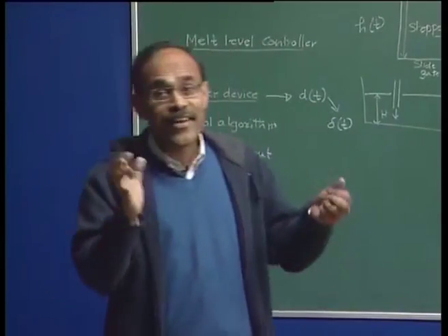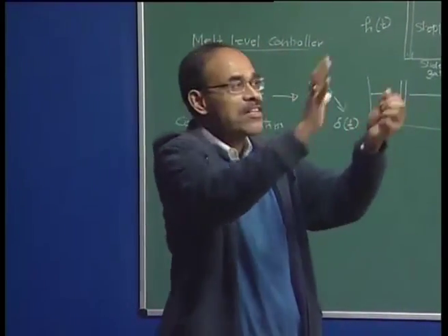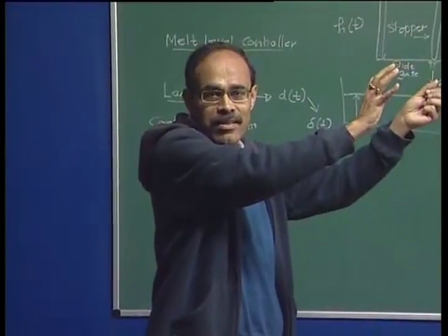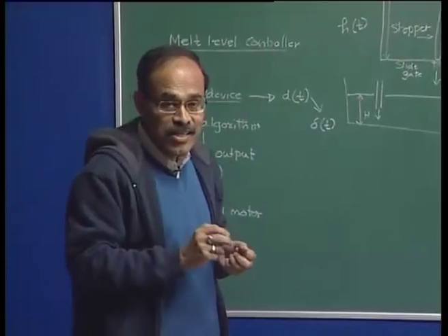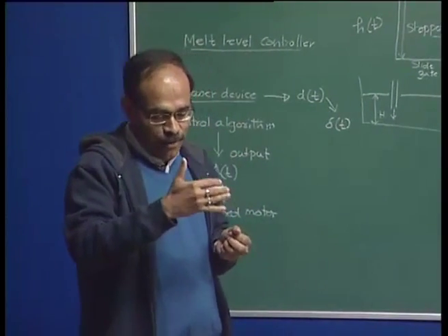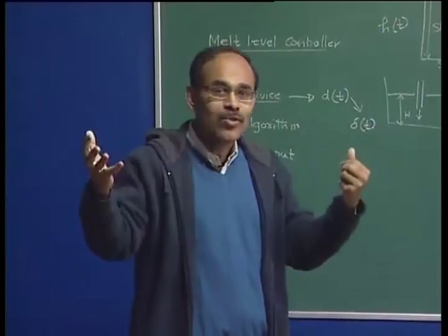So, today the trend is to carry out primary steel making, or mostly decarbonization, in the oxygen steel making furnace, and then tap the molten metal and carry out all these operations in ladles. And once you have set the correct temperature, correct cleanliness, correct composition, you are all set to cast molten steel